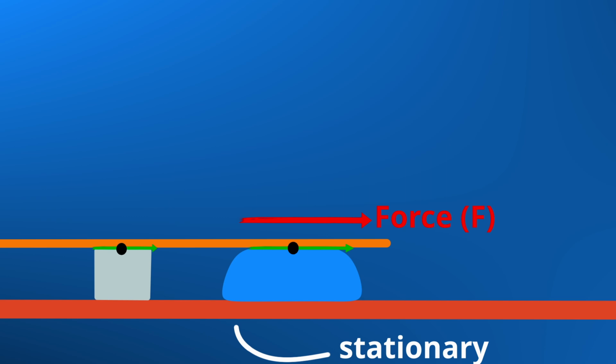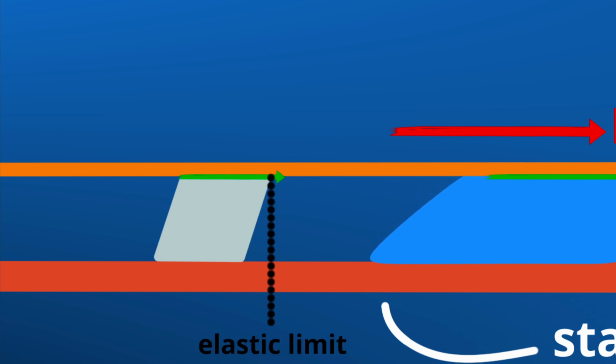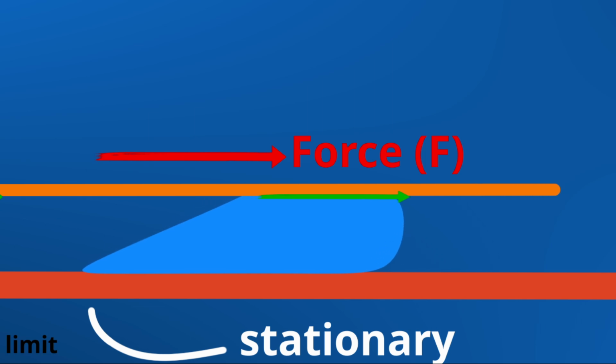Another way to look at solids and fluids is in their ability to flow and deform. If we have two plates, and the one plate on the bottom is stationary, while the one on top is moving with a force F, this will cause a shearing stress at point of contact with either the solid or the fluid. Shear stress is simply a stress felt parallel to a surface. The solids resist an applied shear stress by deforming until their elastic range limit is reached and then stop deforming. But fluids deform continuously under the influence of shear stress, no matter how small.